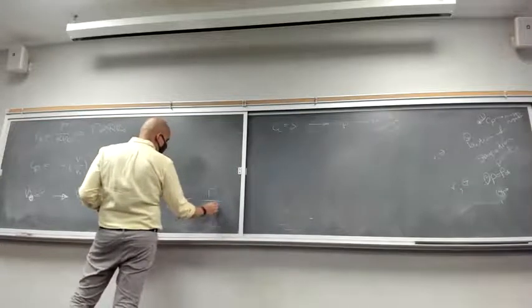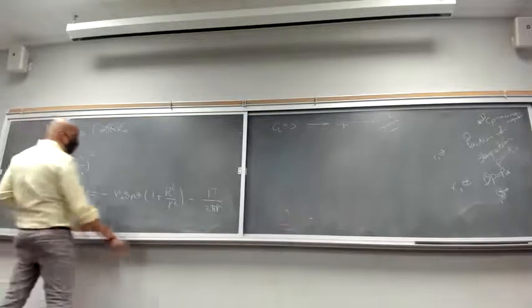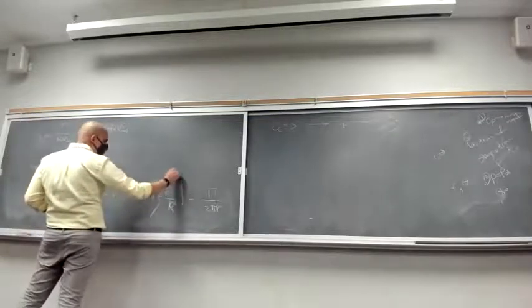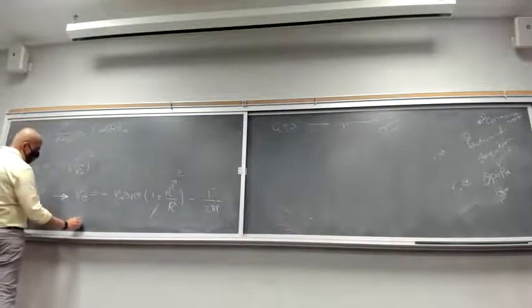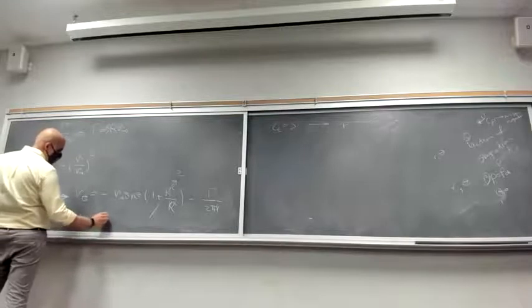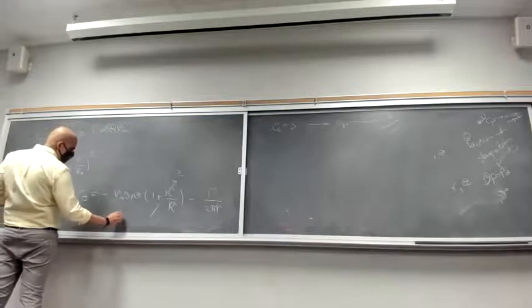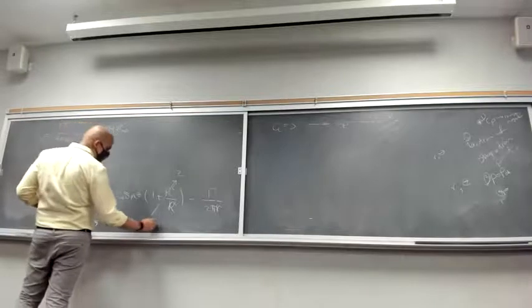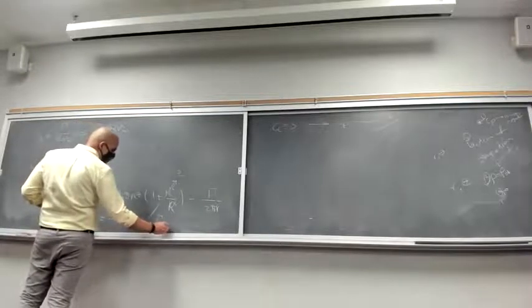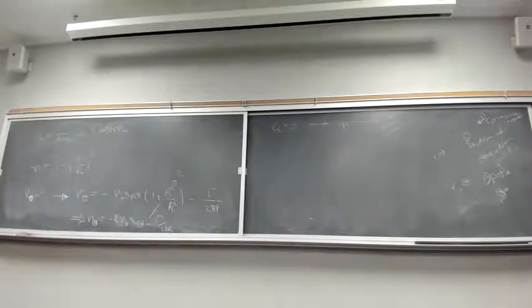And we are looking for this value of CP, most negative CP, on the surface. So r is R. We're going to get 2 here. What are we going to get here? So V theta is going to be equal to negative 2 V infinity sine of theta minus gamma divided by 2 pi R. Okay, just plug gamma in.